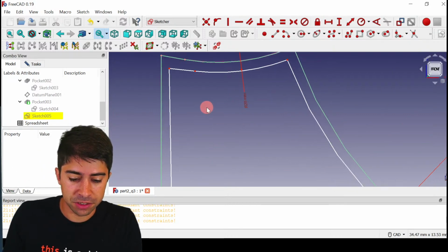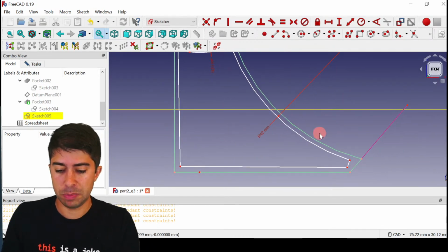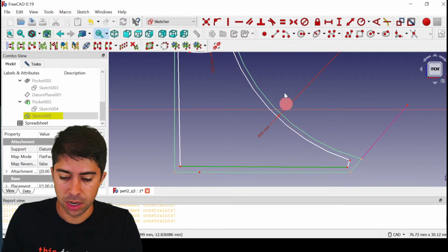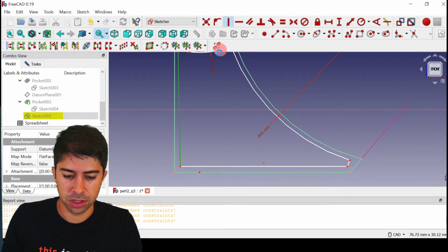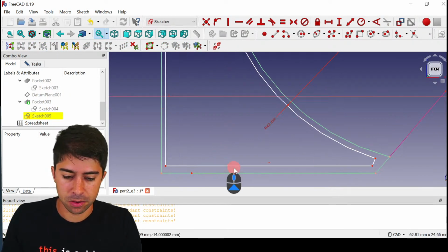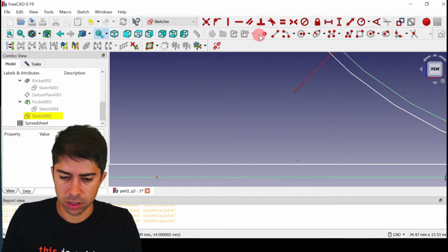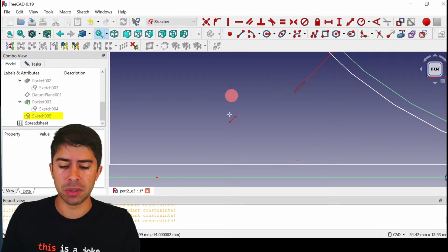Now the only thing left to do is to create our little construction lines for the straight parts, and we can also just go and say for these ones that are actually straight and vertical, just give them relationships. Okay, so that's fine. And now we can go here and do our construction lines. So we link them. When they're blue, they mean they're construction lines.